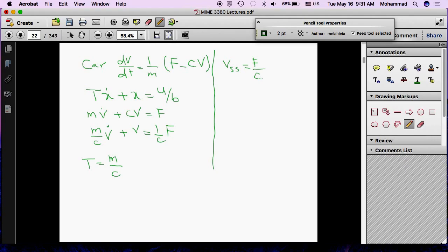Yes. So, see if I have this right. We have a set velocity that we want to get to. According to this, the time it takes to get to 63% of that is proportional to the mass over the drag. So don't you need that drag in order to balance out the forces and slow that car down, essentially? So that way you meet that specific velocity you're trying to get to?